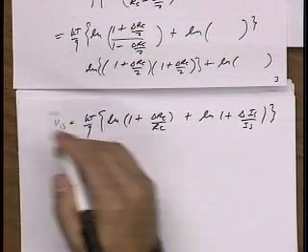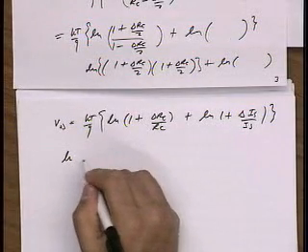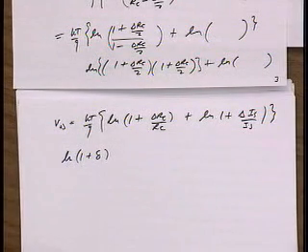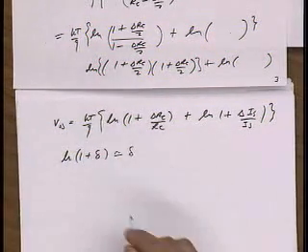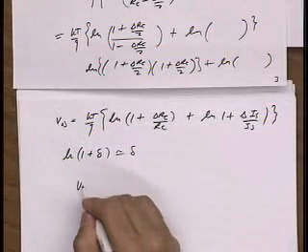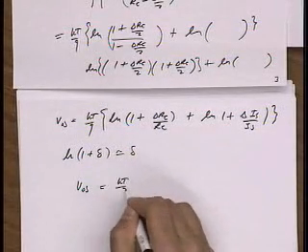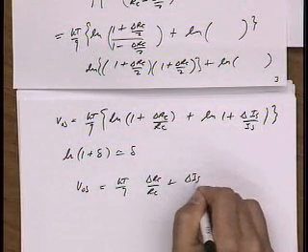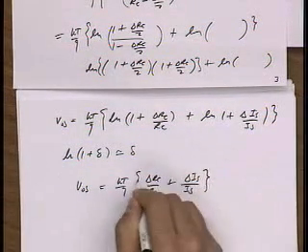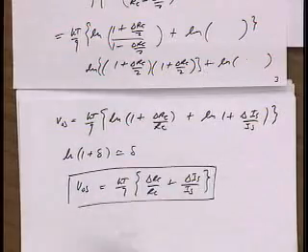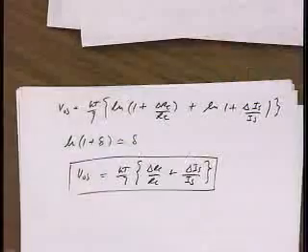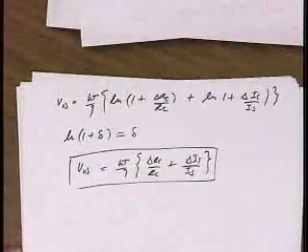Okay? And what's log of 1 plus delta, where delta is small? Yeah, it's about delta. So applying that approximation here, then I just get KT over Q delta RC over RC plus delta IS over IS. And this is a simple enough expression that I can stop here. Okay? Any questions or comments about this calculation?